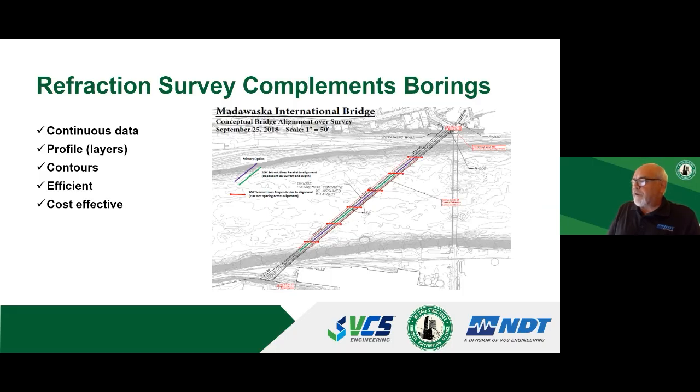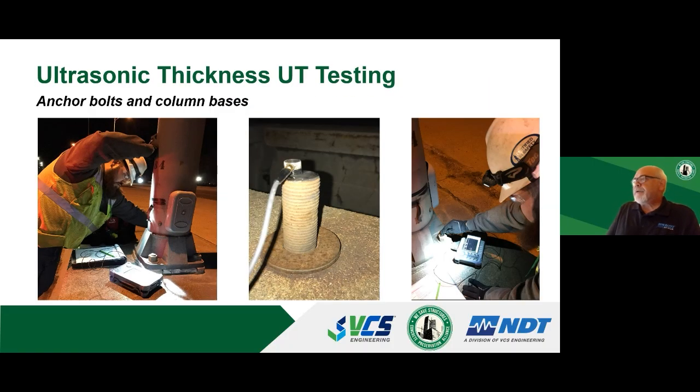Continuous rock profile proved that the rock was a weathered shale capable of the bearing capacities that the spread footings were going to produce on it. And it was between 14 and I think 18 or 19 feet down, continuous with a profile. So that was valuable information. We did this in 2 days. You'd take an awful lot of borings to do 1,400 lineal feet in a lot more than 2 days.